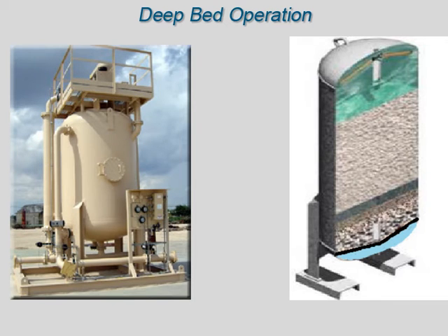When the filter is in service, water is pumped through a distribution pipe above the deep bed. The water is filtered as it percolates down through the granules. Charcoal granules will filter out organic matter, chlorine, and fine particles, while anthracite granules only remove the particulate. The water collects in the bottom of the tank below the support screen and leaves the filter through a pipe in the bottom of the filter vessel.